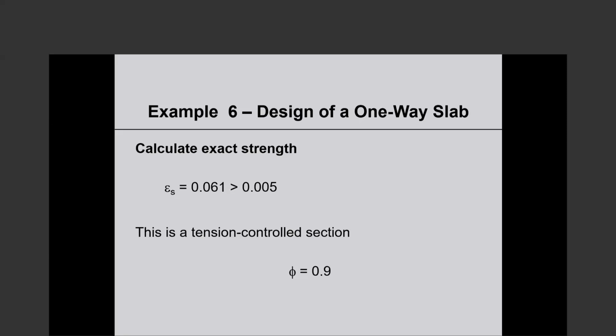With low strength concrete, you will not be utilizing the high strength of the reinforcement. The stresses that you will be imposing on the reinforcement will be significantly lower than the stresses that reinforcement can resist. So it is allowed, but it is inefficient.